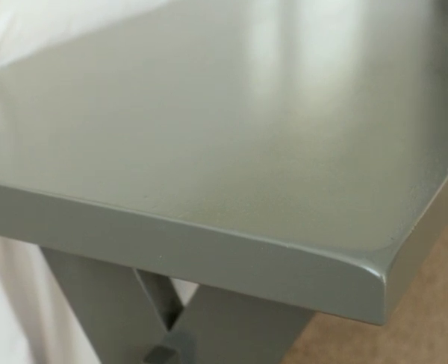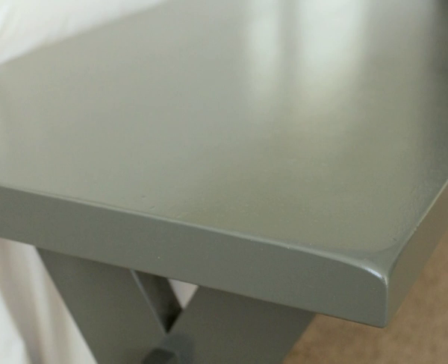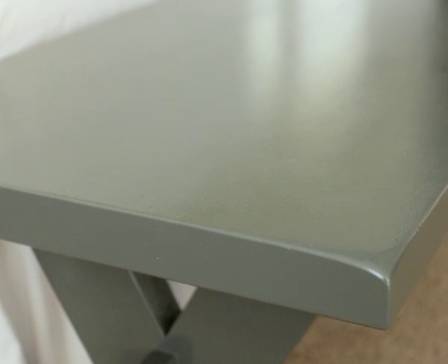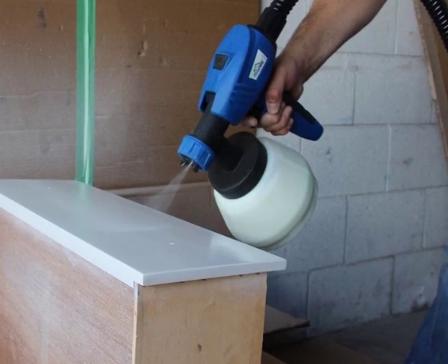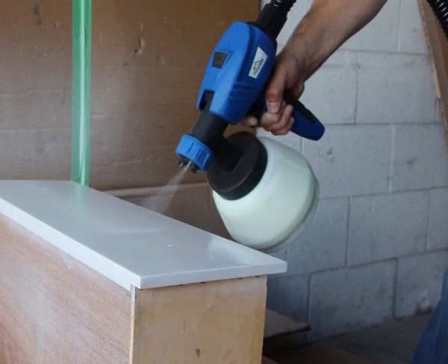If the surrounding film is appreciably conductive, a thicker film with a larger number of pinholes may perform satisfactorily, for under this condition corrosion at the site of imperfections may rapidly choke itself, whilst the thick film does not become cathodic.